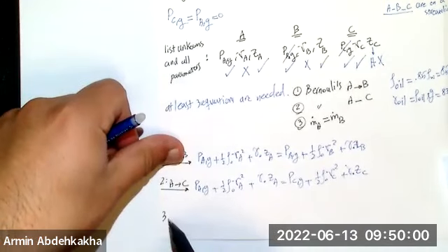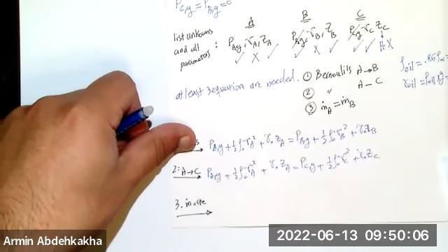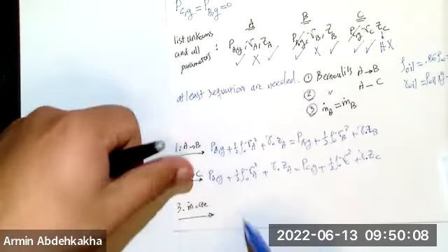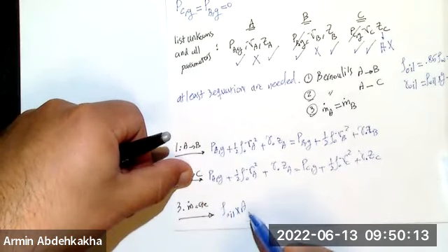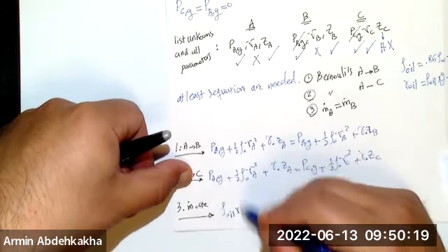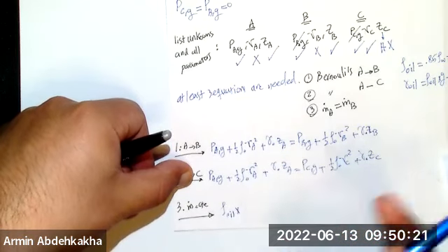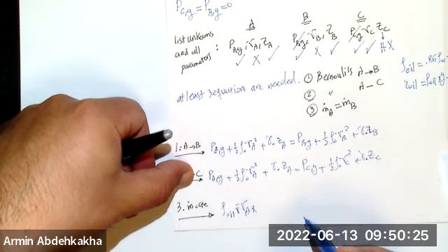And equation 3 is that m dot is constant, right? Okay. What's that? Rho of the oil times area at point A, rho V A. That's better to write in this way. V_A times area at point A, right?